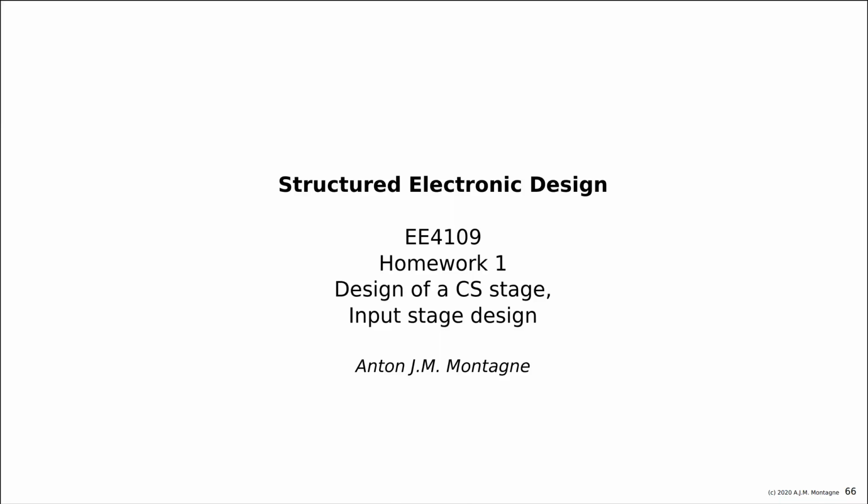But if so, then we could do this completely in SLiCAP. And that's what we are going to do. We are going to design the input stage, the noise performance, in SLiCAP. And then later, if we have initial values generated in this way, then we can go to a test bench in LTSpice and see if we are getting the correct values there as well.